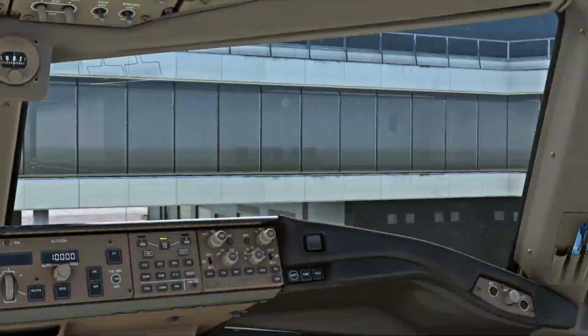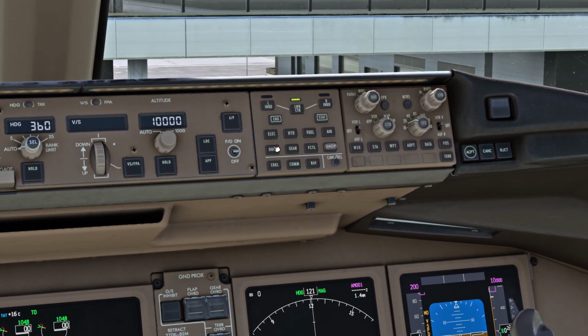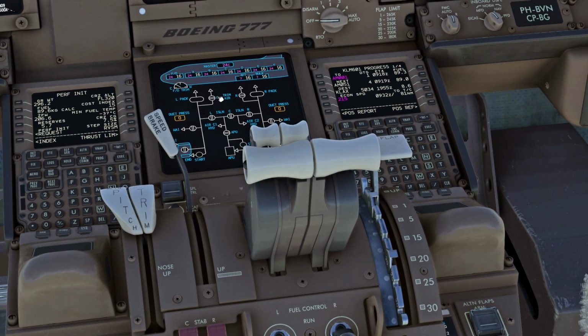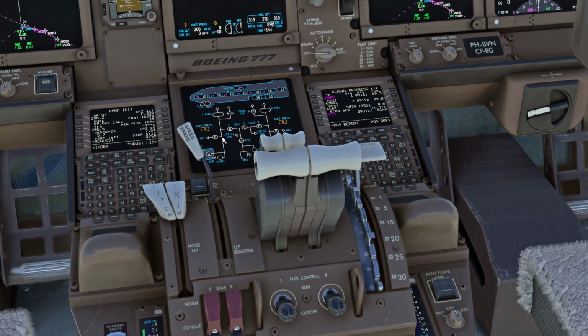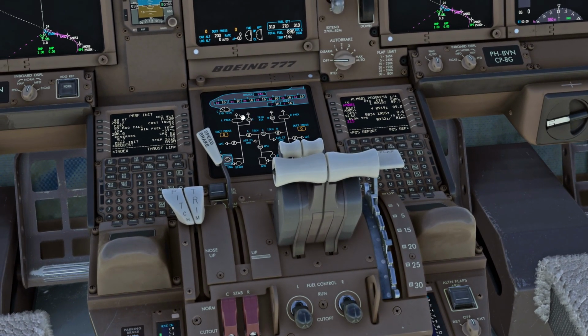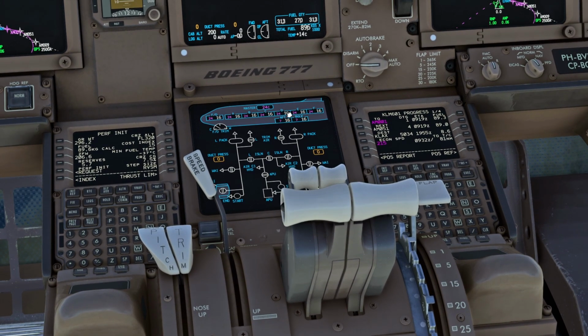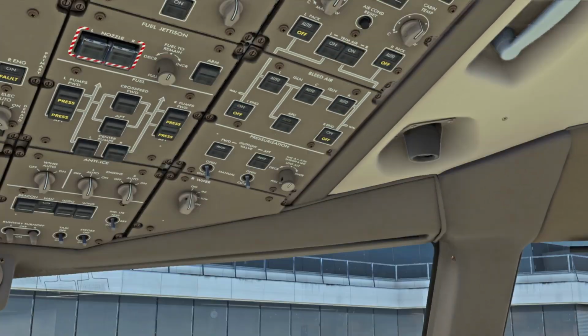The rest of this panel again is very nice through the display select panel to view the synoptic of the system. Right here you can see how it operates and through the different phases of flight. So as you study this airplane, it's very nice to keep these pages open. You can see, for example, the flight deck temperature. The target temperature is 24 degrees, but it's currently 16 degrees in this area. So the magenta is the target and the white is the current temperature. As we do not have any bleed sources yet, no APU or engine started, it will not warm up yet. So if it's a very hot day or a very cold day, you would start the APU early or use the ground air system. Okay.